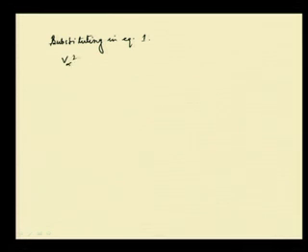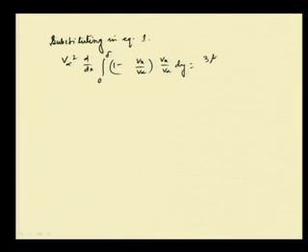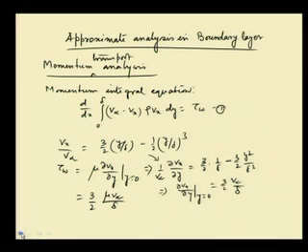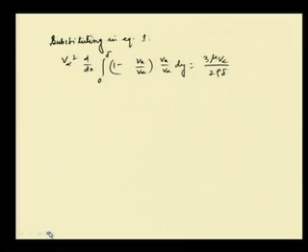we get V infinity square d dx of integral 0 to delta (1 minus Vx by V infinity) into Vx by V infinity, because our velocity term is in the form of Vx by V infinity. Therefore, we are dividing by V infinity to get this expression, into dy, and that is equal to tau w replaced by 3 mu V infinity by 2 rho into delta. That is what we have seen in the last derivations. Now, there will be a rho here, because rho has been taken to this side.